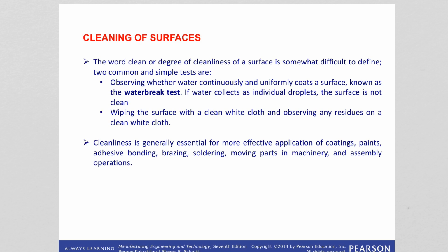A clean surface can have both beneficial and detrimental effects. Although a surface that is clean may increase the tendency for adhesion in sliding, thus increasing friction, cleanliness is necessary, we know, for applications such as coatings, paints, adhesive bonding, brazing, soldering, and welding operations.